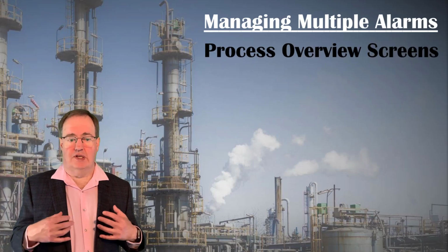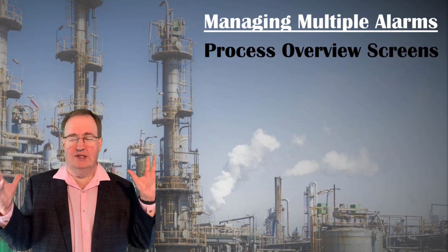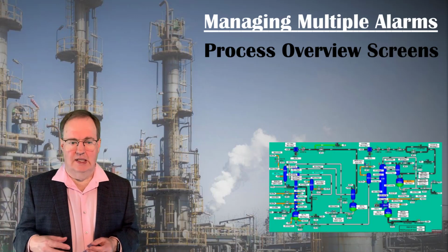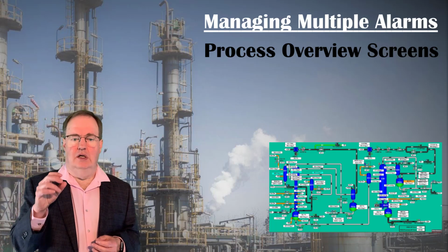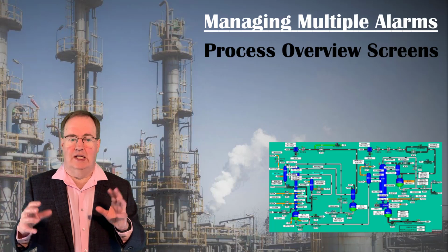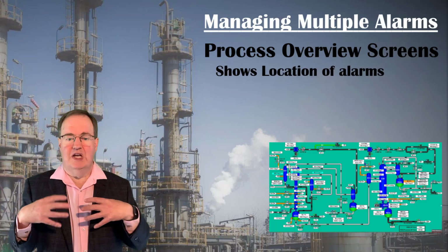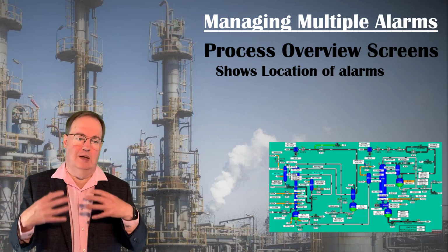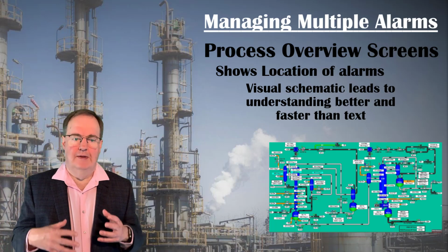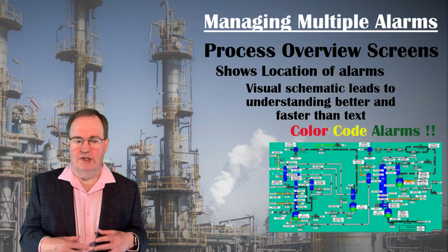Much more useful as a communications tool for alarm and crisis management are the large process overview screens discussed in the previous lecture on graphics. If alarms appear on a process schematic, color-coded as to their severity, the location of the problem will be immediately apparent, which makes it much easier for an operator or engineer to understand, react, or troubleshoot. Always color code and animate alarms on process screens.